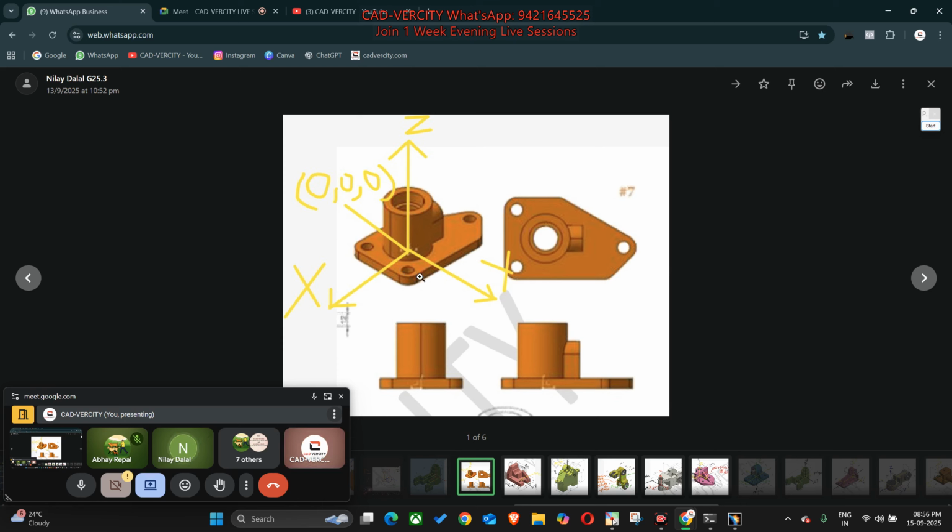XY plane. Why? For the cylinder, Y plane. Why? Which command are you going to use? Revolve command, if Y plane. Okay, if I don't want to use the revolve command, the surface will be extruded in the sketch we have drawn in the XY plane, and then we will extrude that boss. Perfect.